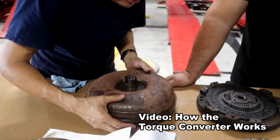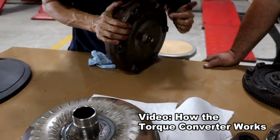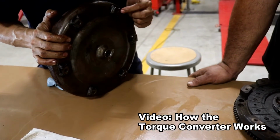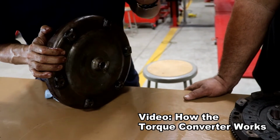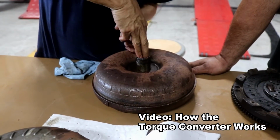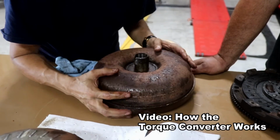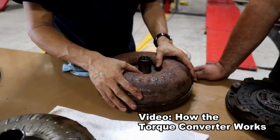Look at this. This is the housing of the transmission. Remember that this housing is bolted on the flywheel, and you have access to those bolts if you remove the starter motor. That's simple, the procedure to remove this one. And where the shaft enters here, you have an O-ring. That's important when you remove the torque converter. Be careful with that O-ring. Normally the color is orange.